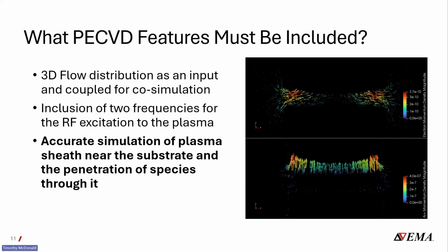The key features are the thickness. In this type of plasma, the sheath is very thin compared to the overall plasma. It's measured in microns versus the overall plasma, which is measured in centimeters. The sheath acts like an insulating skin between the plasma bulk and the surface. And the sheath directs positive ions toward the surface, at high energy.